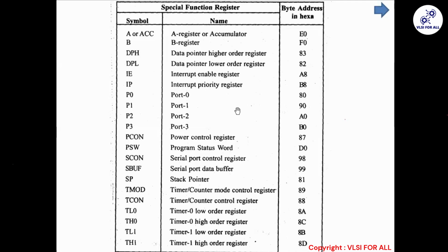In the washing machine, though I am turning on the main, setting the program and turning on the program, my program will check for interrupts. Which two interrupts am I talking about? One is whether the tap is running, whether there is water in the tap, as well as whether the door of the machine is closed or not. What I told you, door closed or not is the second priority. The first priority is whether water in the tap is there or not. That priority you can set using this register IP, and enabling those two interrupts happens in the interrupt enable register.